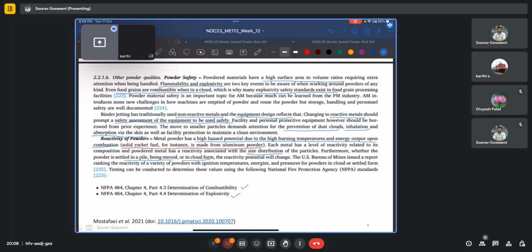Okay. So I can tell you a couple of reasons why the parts are aligned in that fashion for, say, the metal powder bed or electron beam powder bed. One of the reasons, as you rightly mentioned, is that the recoater blade can simply come in contact or collide with the parts. To minimize the length that is in contact with the roller or the blade in each pass, we tilt them at an angle.